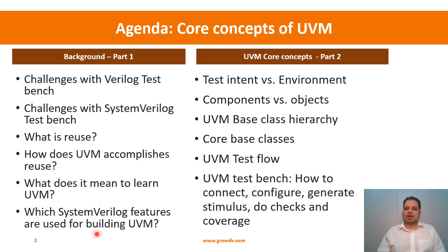Once we do that, we will have a good context to jump into the core concepts and the key base classes. So we will jump into that, and then we'll look at a little bit about how the UVM test benches are created, and then we'll go into some key concepts like what's the test intent versus the environment, component versus objects. Some of these terms we have introduced. What is the base class hierarchy, and then whatever the core base classes, we will understand at least a quick formal definition for each one of them as to what they are intended to do.